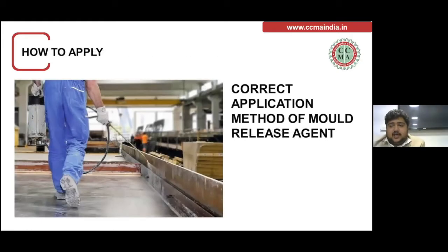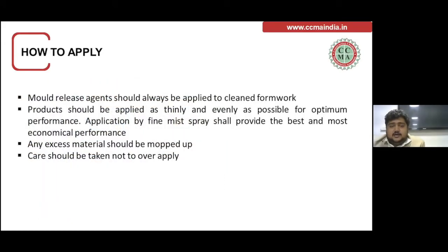So how to apply? The correct method is that the mold release agent should be applied on clean formwork. There should not be any residue of earlier use, and it should be very nicely clean. The product should be applied thinly. It should not be applied like a paint. It should be applied as thin and evenly as possible to optimize performance.